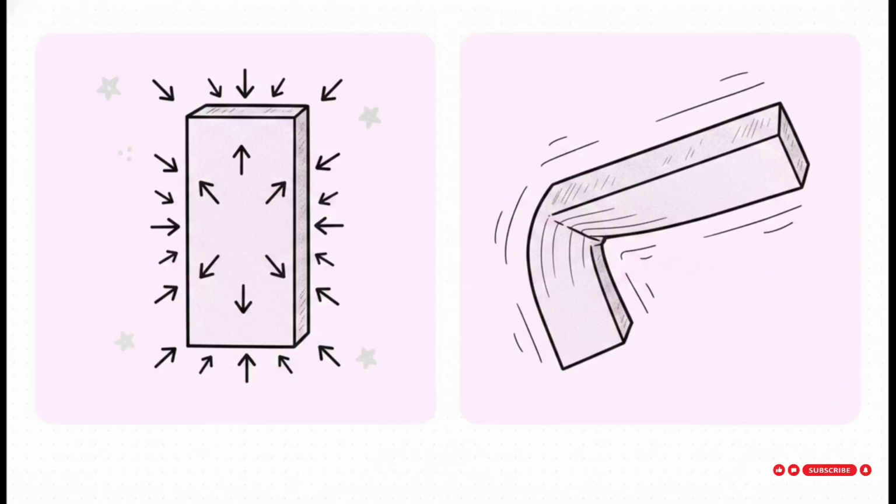And that brings us to the ultimate duo, stress versus strain. Now, stress is the internal balance of compressive and tensile forces within the metal itself. Our sources highlight that you can actually see internal stress indirectly through things like springback, which, if you don't know, is when a rolled strip of metal increases in diameter after being removed from a holding mandrel. Strain, on the other hand, is the physical result of that stress. It's the actual elastic or plastic deformation of the material. Think of it like this. Stress is the invisible load, while strain is the visible distortion.